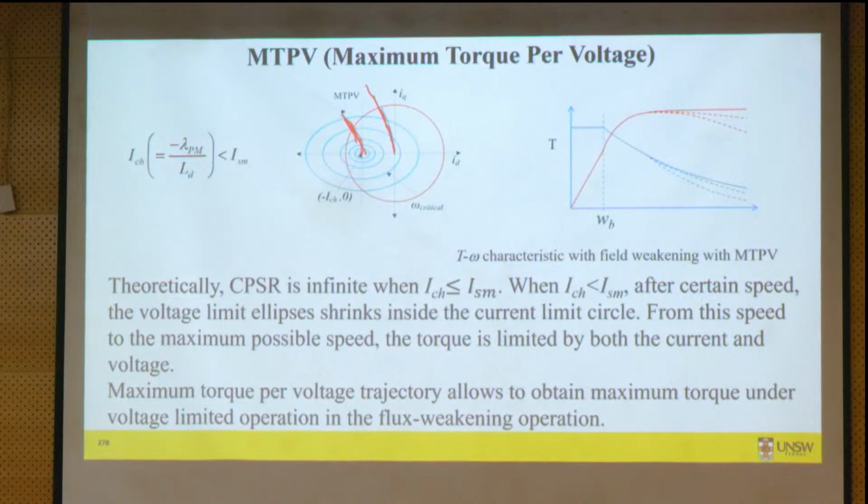So the motor with very deep flux weakening, IPMSM, operates first in MTPA up to base speed, then operates with flux weakening here, and after that, once it sees the MTPP trajectory, it will operate along the MTPP trajectory. And for MTPP again, there is another way of calculating the negative ID current. So it all becomes how to calculate that negative ID current in IPMSM for all these controls.